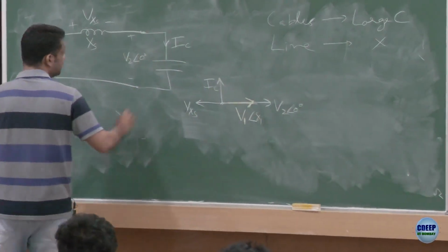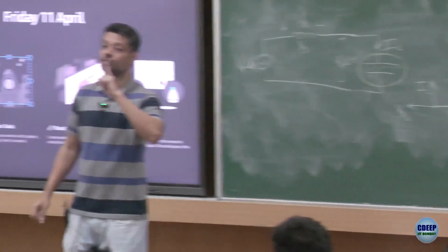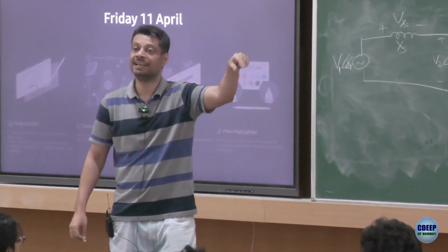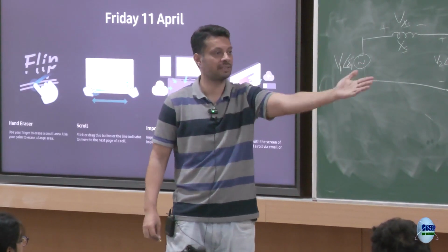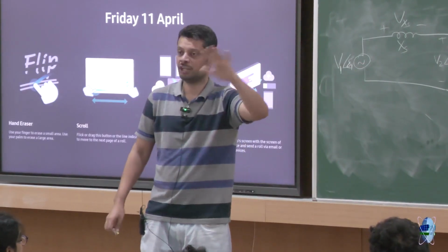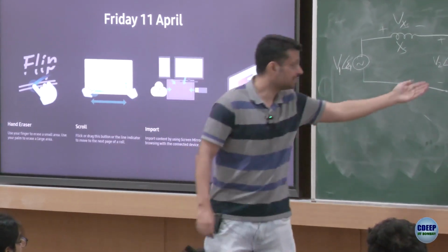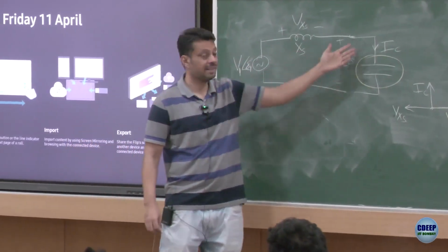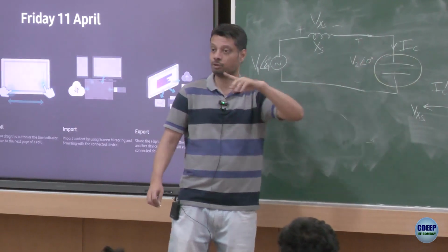And this capacitor could be the one capacitor which you had connected in the load side to compensate for the inductive load that you generally have. But let's say today the inductive load is turned off, night has come and the inductive load is turned off. So the inductive load goes off, that compensation has no meaning now, but your capacitor is still stuck there. So now what will happen in night? You may see much larger voltages here than what you expect, right? This could be one reason.